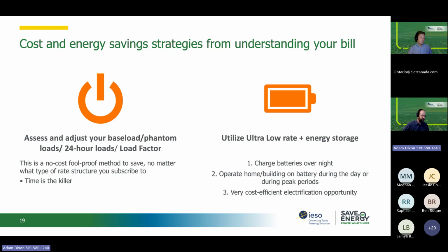That's when I first got into the energy management world. I was doing small house audits, and my boss said that in the residential world, it's death by 1,000 cuts. It's rarely ever one thing in your building that is causing your electricity load to be out of control. It's usually a combination of a lot of little small things and the things that are running for long periods of time. There's a good chance that at home, the little clock on your microwave actually uses more energy than the microwave itself when running, because that clock is at about 5, 10, maybe a bit more, depending on your microwave's watts, and it runs continuously.